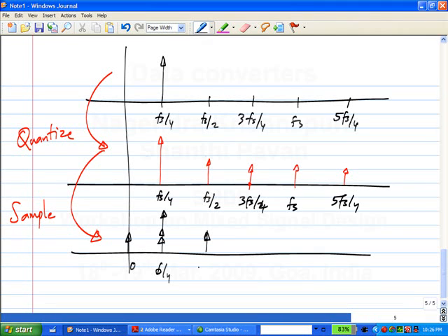So I am showing this to point out that quantization noise, I said, will give you some noise-like spectrum, but it's not always true. You can always pick the ratio of input frequency to the sampling frequency so that it looks something weird like this. There are only 3 tones here. There is no noise.